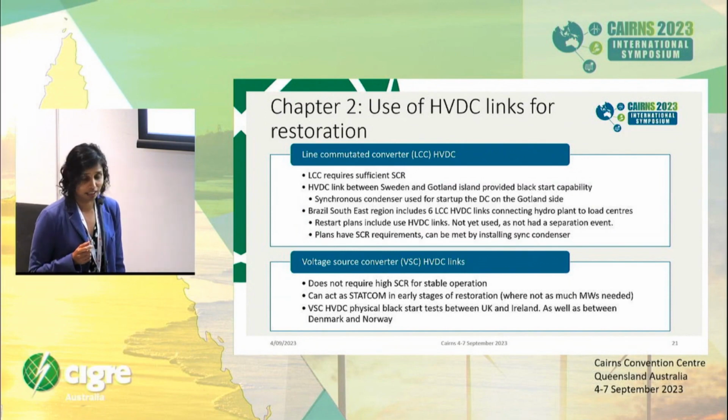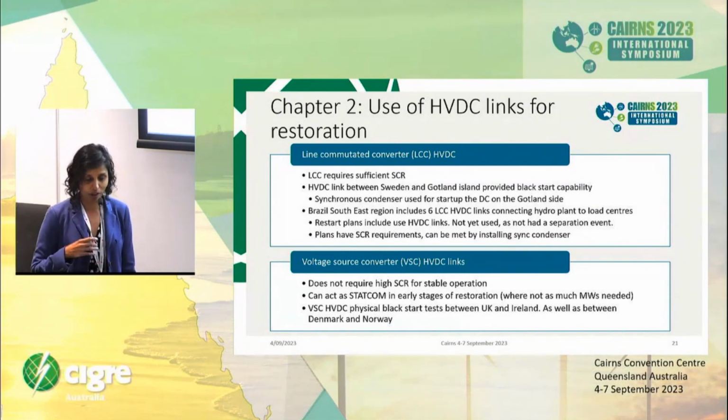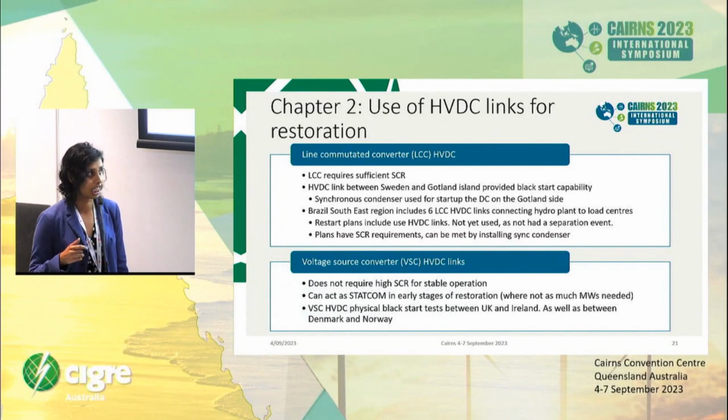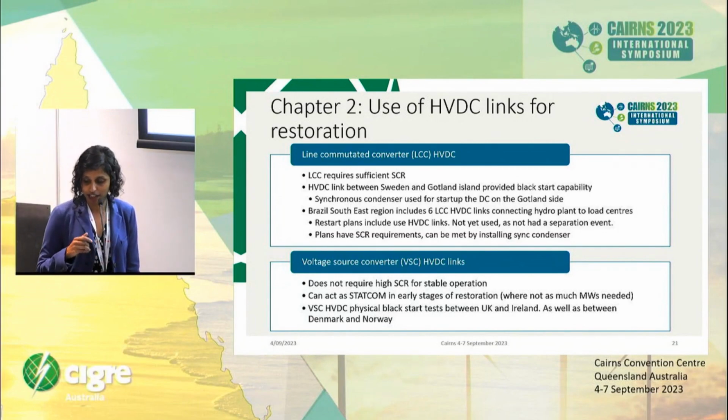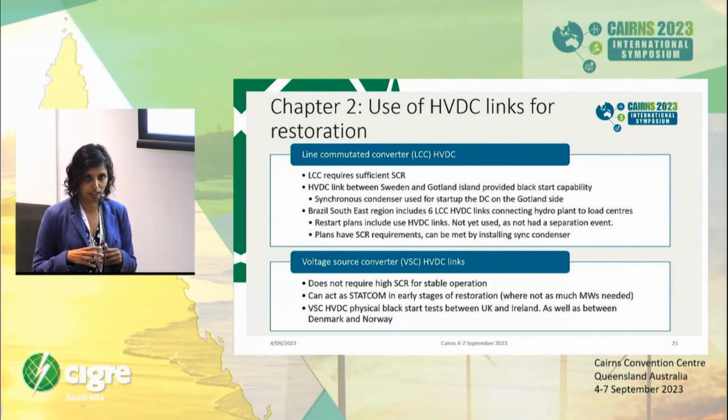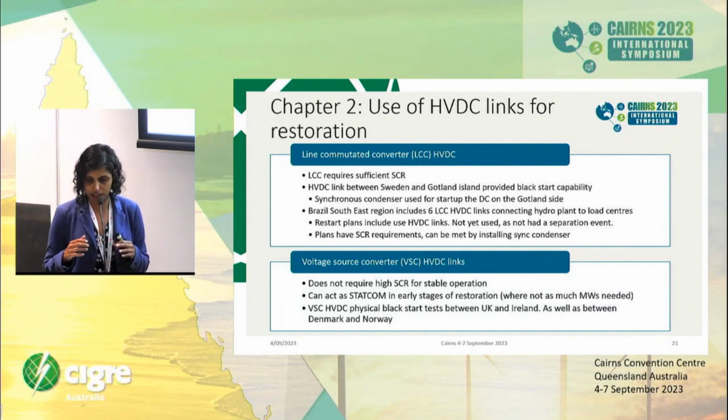In the Brazilian southeast region, their operational restart plans also consider their LCC HVDCs, of which there are 6, connecting large hydro plants to load centers. And these plants have minimum SCR requirements that need to be met for these LCCs to be operated stably, and they consider potentially installing synchronous condensers.